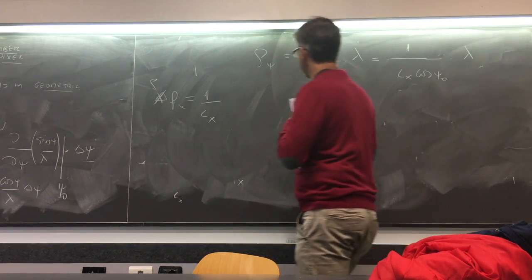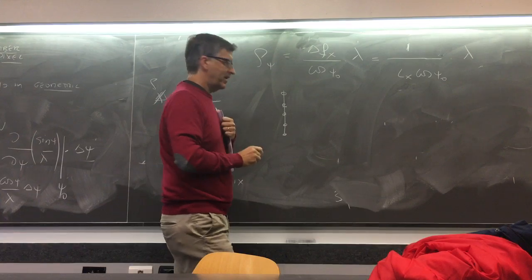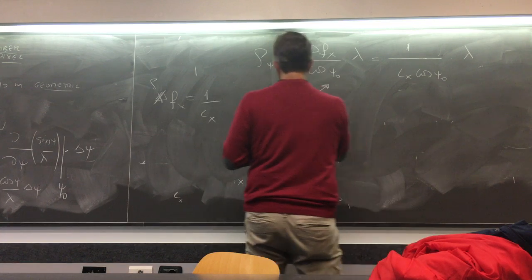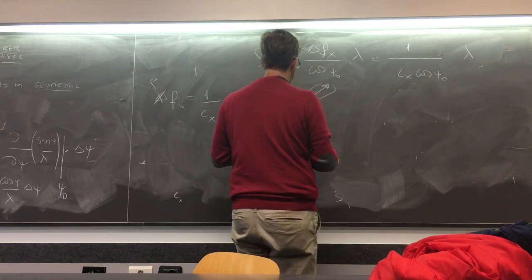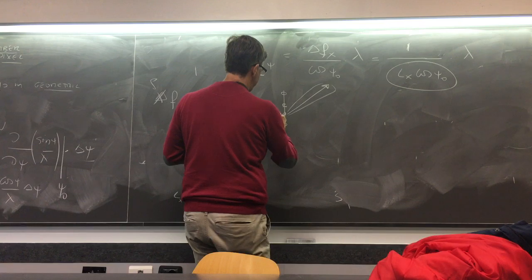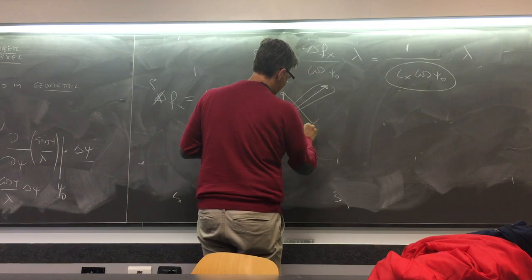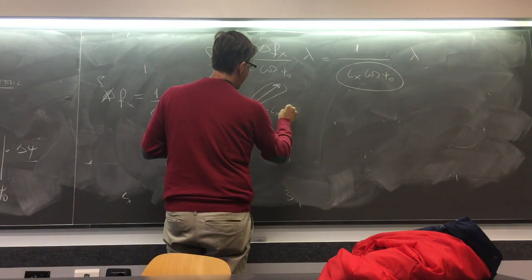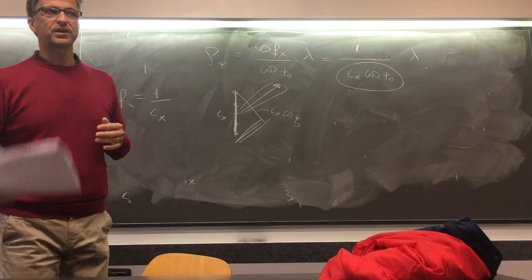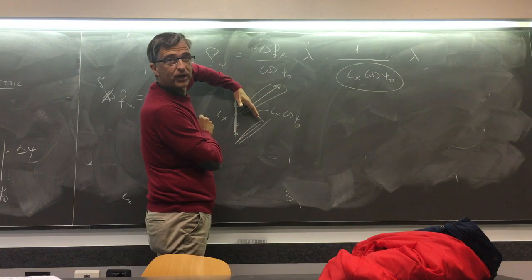So what I'm telling you is that if you have an antenna array, and you want to look in this direction, the resolution is similar to the resolution of a real antenna that has these sides. Why these sides? Because if Lx is this, when you point in this direction, the orthogonal length is here, Lx multiplied by cosine of psi. So the resolution is always proportional to the side of the equivalent antenna orthogonal to the view angle.